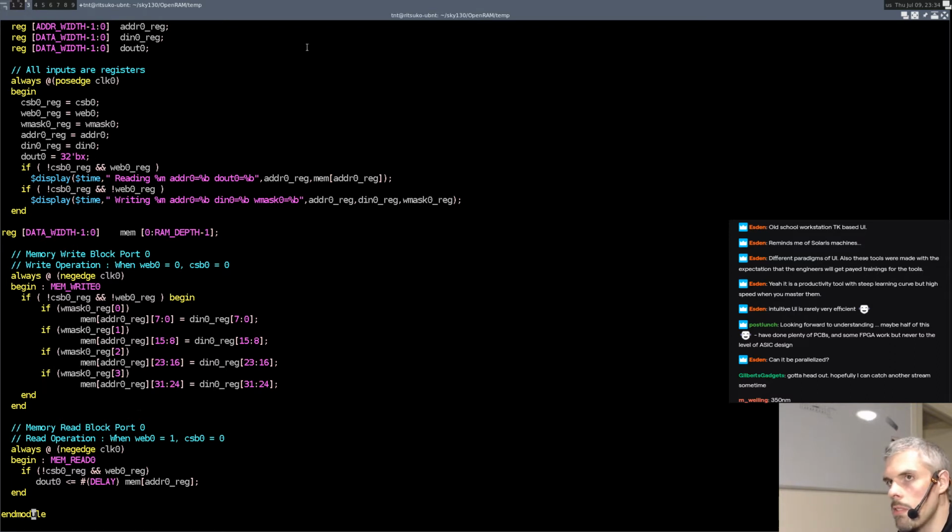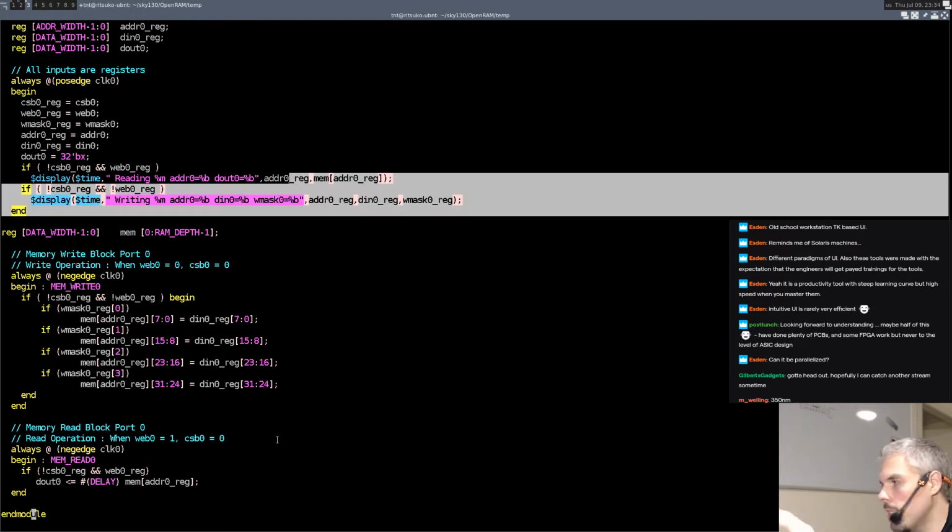So previously we saw that there was a clock to out of like 6 nanoseconds, but really if you're clocking your design and you have a clock period of 20 nanoseconds, 10 nanoseconds is just going to be lost to the pre-charge, because that's half the clock cycle.